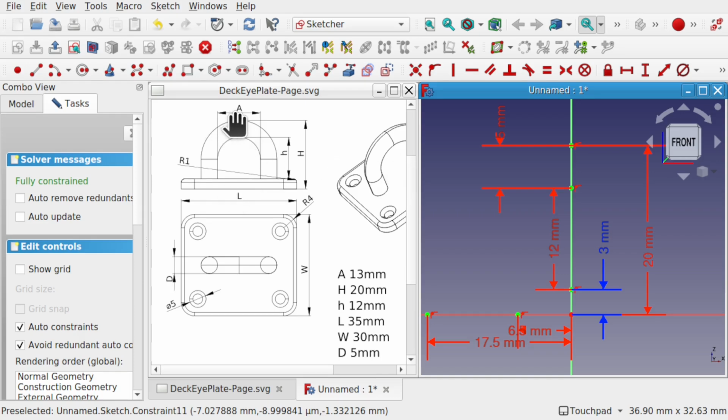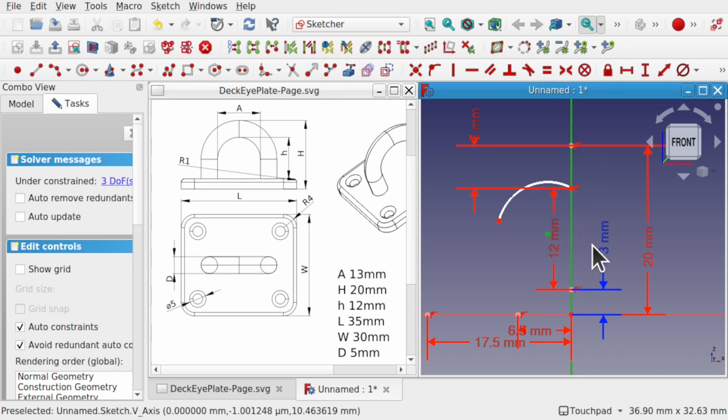First of all, we need to figure out this arc here and whereabouts it sits because we haven't got any height here. We can see where this arc will start, which is this point here. So let's place an end point and rim point arc in. Remember, this is still using this just to rough this out. So I'm going to place an end point and rim point, and I'm going to take this point and attach it to this vertical axis here with a point and line constraint.